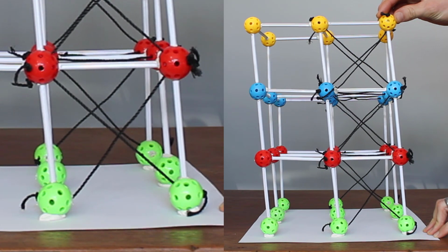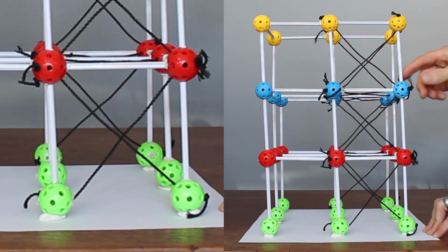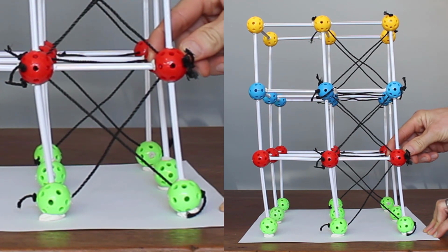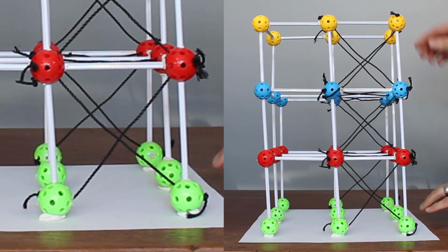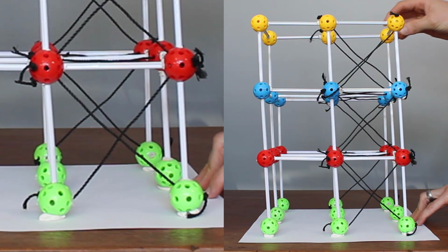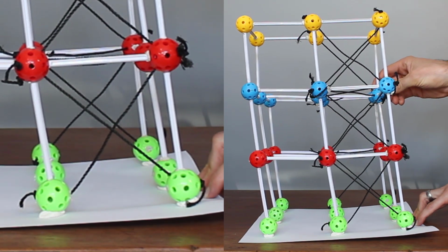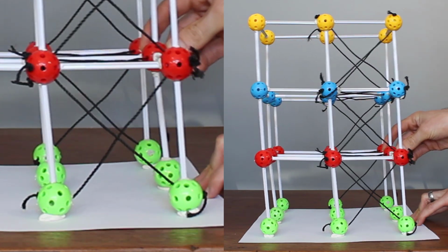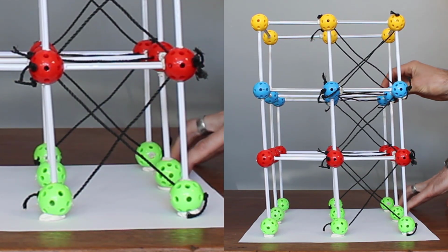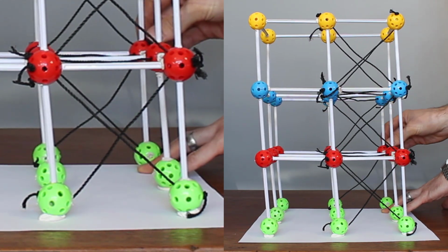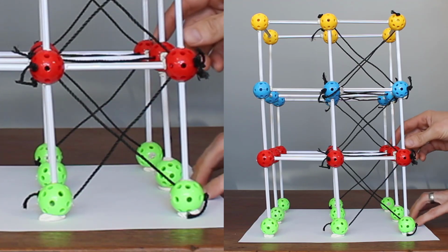Now, loading it with the bracing, here you can see a zoomed in view and a normal view of the structure, and you can see how as we load it, the one side wants to lift up, the foundation actually wants to lift up in tension, and then the tension bracing carries load while the compression bracing just buckles out the way. You can see how if we load it at different levels, everything from there downwards is stressed, and from there upwards is not stressed.